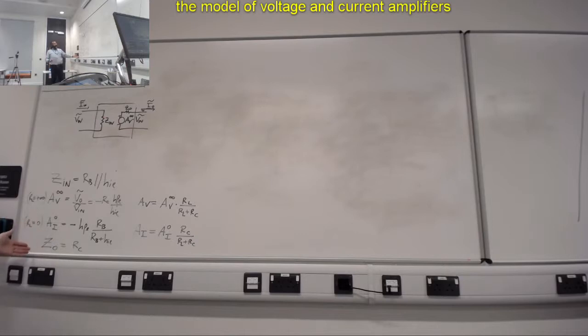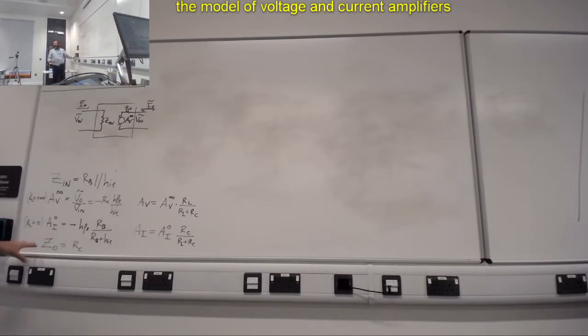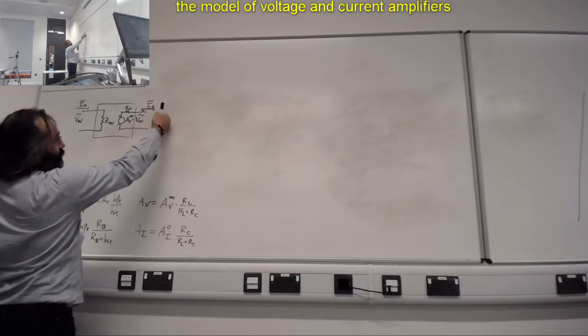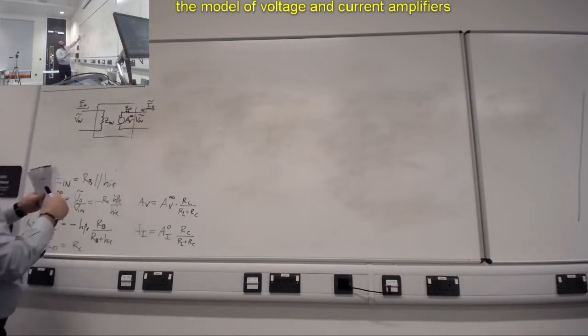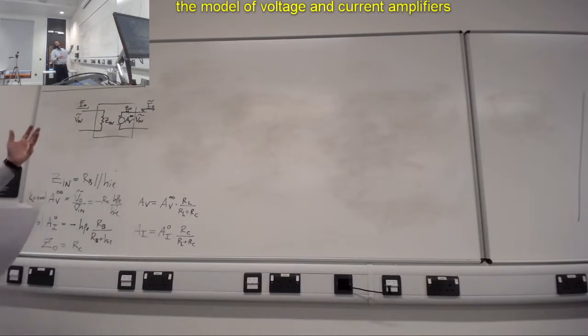Based on the definition we've used of Z0, the output impedance. Why did I connect it like that in series? Because the output impedance, we've defined it as the impedance I would see from this point of the circuit if I was to assume that this side is at 0, the voltage is 0, or the current is inexistent.